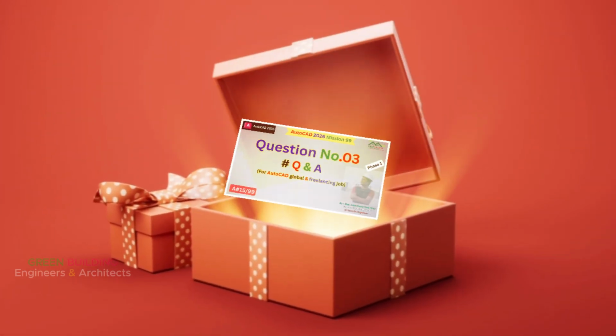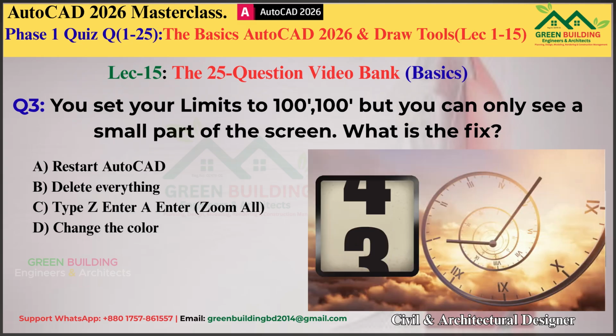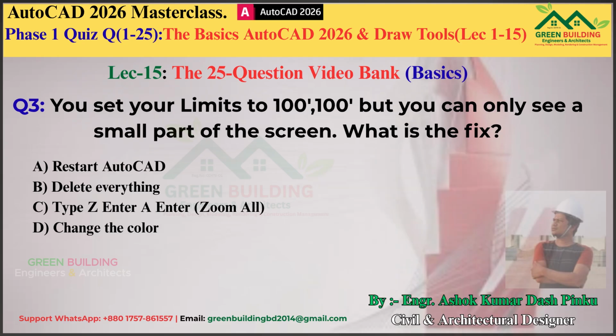Now question number 3. You set your limit to 100 feet by 100 feet, but you can only see a small part of the screen. What is the fix? Option A, restart AutoCAD. Option B, delete everything. Option C, type Z, enter, A, enter, zoom all. Option D, change the color. The correct answer is C.